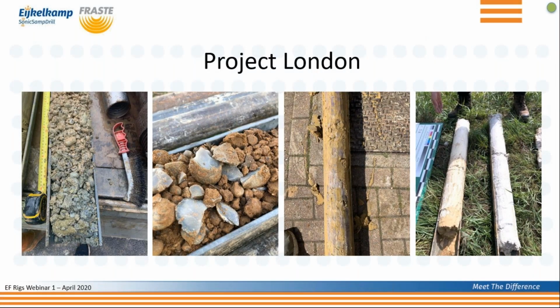So can you give some examples of jobs you've been doing with CP? How long did it take to do that, and how long does it now take to do it with sonic? A typical one comes to mind in an area around Slough and Reading. It was taking us about 4 days to drill a borehole down to about 30, 40 metres, with SPTs, U100s, that sampling, that kind of thing for a geotechnical firm. With the sonic rig, we were doing one a day and then moving, and getting 100% recovery.